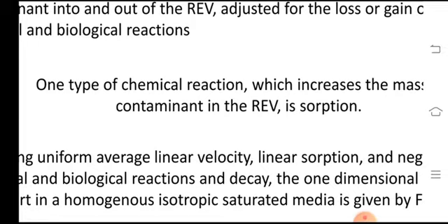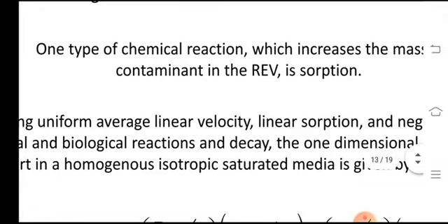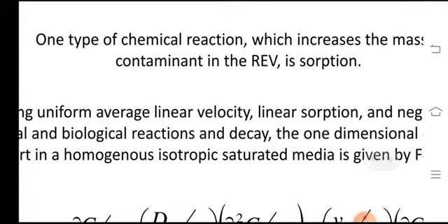So this is the key function of any kind of contamination in a typical environment. If we need to understand the behavior of solute within a soil mass, we must understand the sorption and desorption processes which are taking place within that volume of soil. Based on that we will be developing this equation, and then we can quantify the concentration and its variations, and we can determine the fate of contaminant within our predefined boundary conditions.